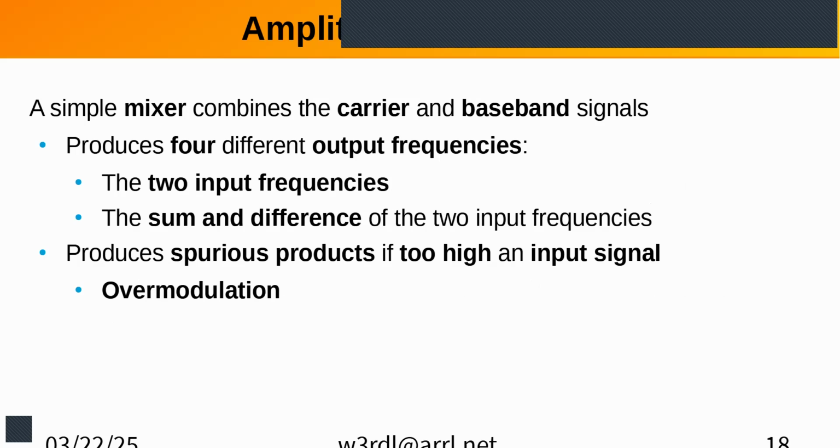So if you're looking at upper sideband and you shift down to where the lower sideband is in your upper sideband passband, now you've got the signal, but it's inverted frequency-wise. Otherwise, all you'd have to do is move up and down and pick either one. But it doesn't work unless you filter one out and flip it to the right one. We'll talk about that a little bit more and confuse you even more. But essentially, remember that you get the sum and difference of the two frequencies.